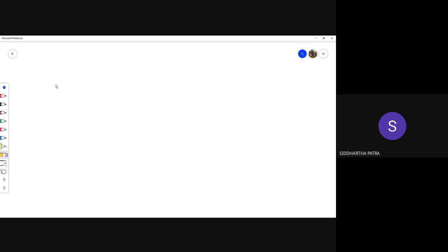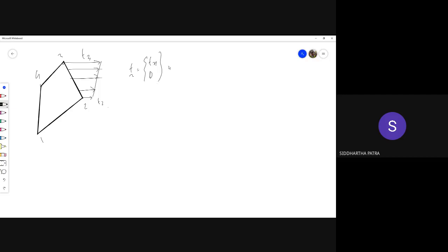And again, now evaluating the traction force, imagine again there is some traction in the x direction. So nodes 1, 2, 3, 4. On the 2, 3 side, there is tx going from t2 to t3. So just like the previous example, the traction is tx and 0, with tx going from t2 times N2 plus t3 times N3, and 0. Now you see N1 and N4 are 0 on the line 2, 3.